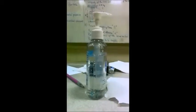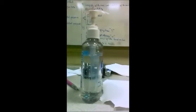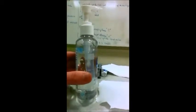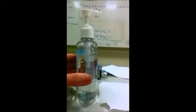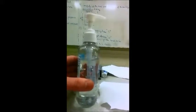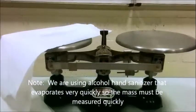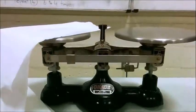It was noted that this fluid is very viscous, and to minimize the effects of this viscosity and the possibility that this might cause the fluid level to be inconsistent, hills and valleys, between each measurement, we will try to even it out by shaking up the fluid clinging to the walls. This will flatten it out to some extent and minimize possible errors. Here, we are balancing the scale with the fluid on top to obtain the mass of the fluid expelled.